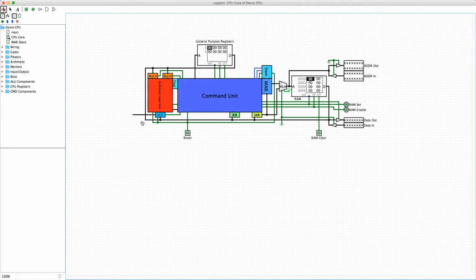Anyways, I based this CPU off of something I saw in a No One Lesson video. I'll link to those relevant videos in the description. In those videos, they show what's inside a CPU and don't really talk about signal control the way Ben Eater did. And the way they did explain some of the signal control was to imply that the clock input was to be put high when you were ready to write data into the register, which kind of led to a few things.